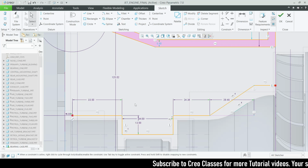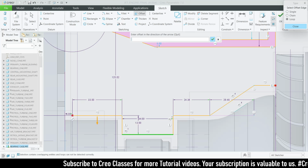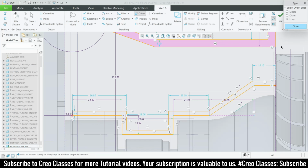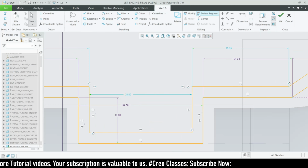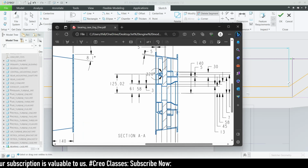Now I'm going to offset this. So go for the offset loop. Select this entire loop, and here I'm going to offset -3. Then, as you can see here, we don't want this because this is a straight line.